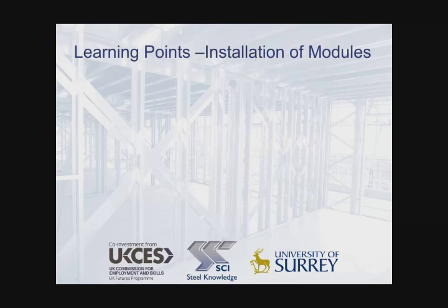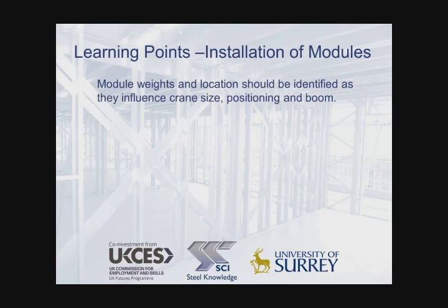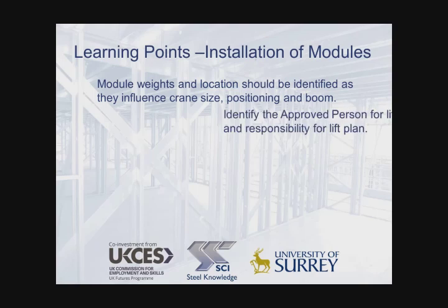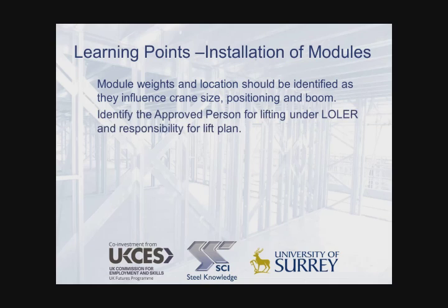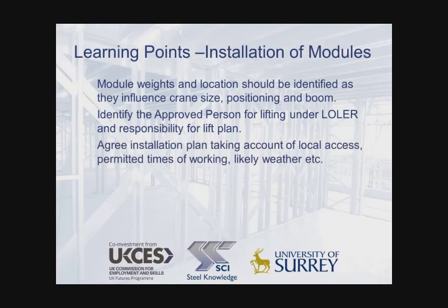So what have we learned regarding the installation of modular units? Firstly, that module weights and location should be carefully identified, as they will influence the crane size, positioning and lifting sequence. An approved person is identified under the LOLER regulations who has responsibility for the lifting plan. It's necessary to agree the plan taking account of local access, permitted times of working and weather conditions.